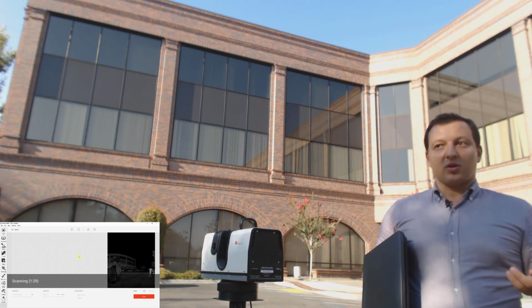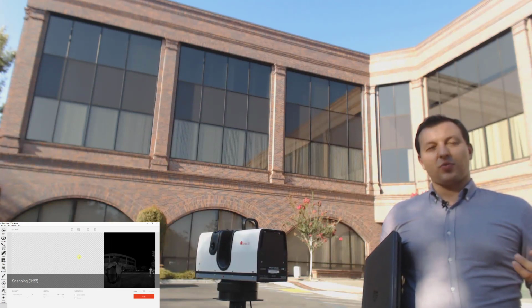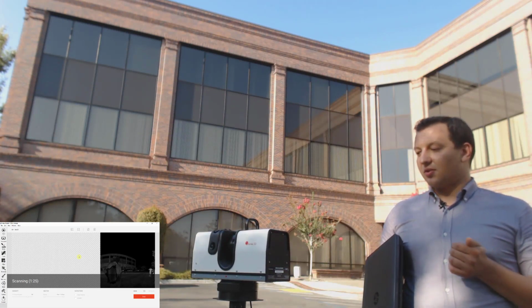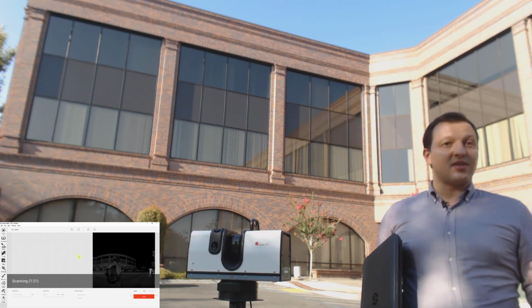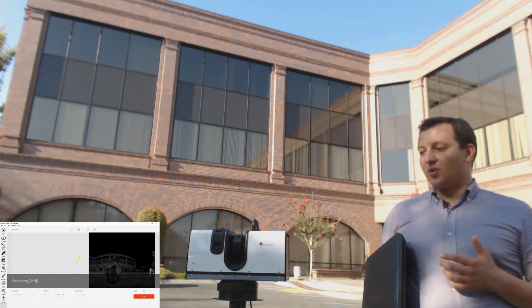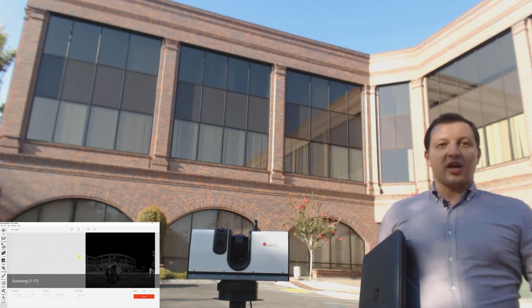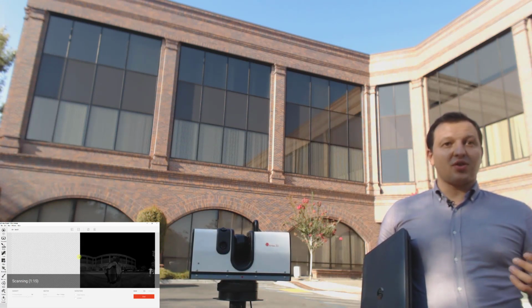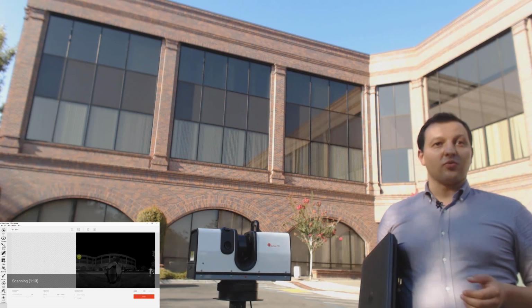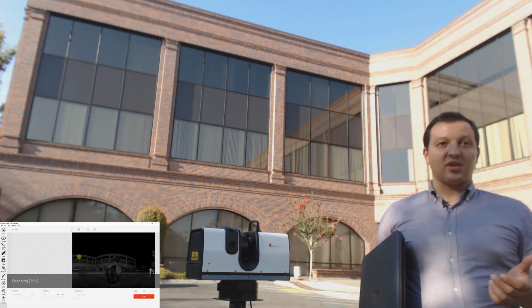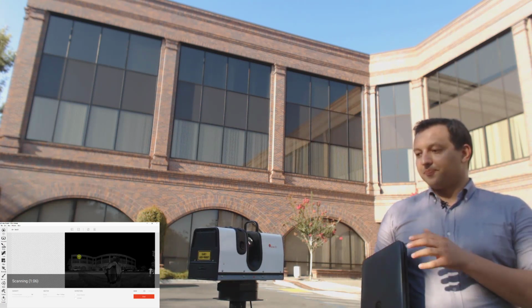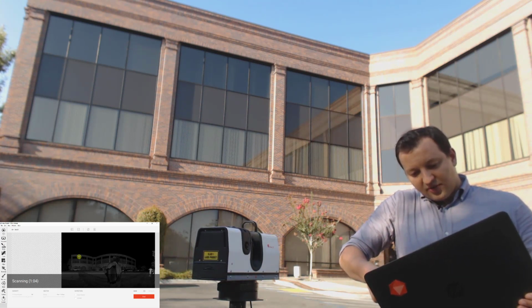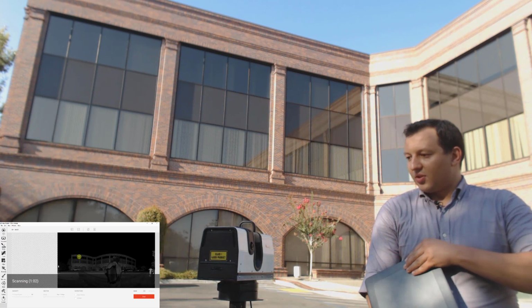At the maximum point density, at the maximum accuracy level, it'll scan at 700 microns, so that's the error on the device. There's also a high sensitivity mode, which allows you to scan shiny reflective objects or objects that are noisier, but with a slightly reduced accuracy of 900 microns. So even at its worst, it still delivers sub-millimeter accuracy. Let's check a little bit on that preview. All right. Still have a little bit to go.